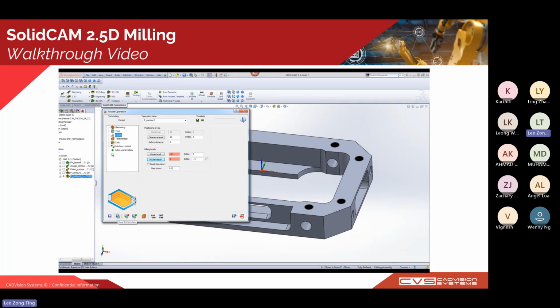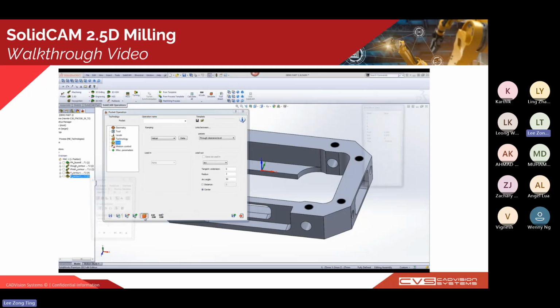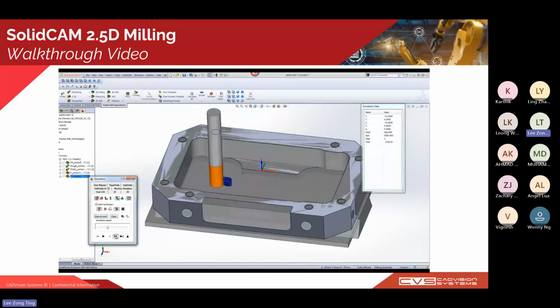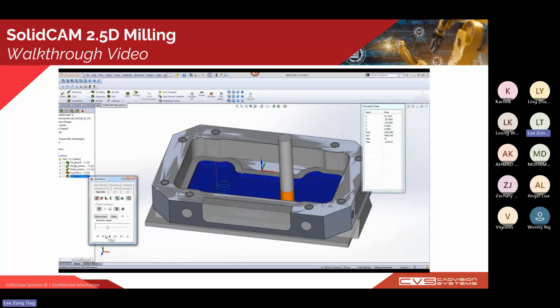So we'll go ahead, and after we input the parameters we want, we'll save and calculate those tool paths. And we can also check for collisions during the simulations. You can see, yep, the bottom pocket operation is a success.